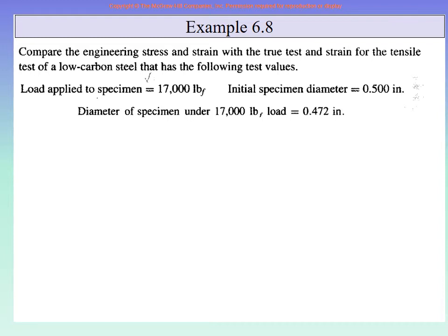Have some of you thought about it? So pause and think about it. You were to think about it at that time when we were discussing true stress strain. But if you did not think about it, pause my lecture and think, can you prove that ln of Li upon L naught is the same as ln of A naught upon Ai?